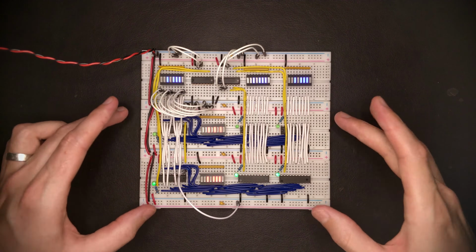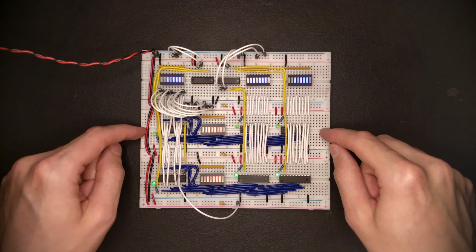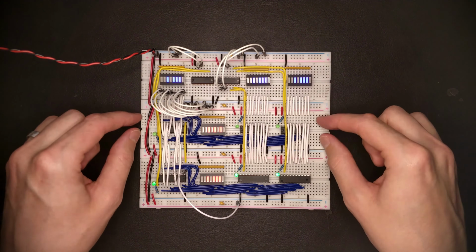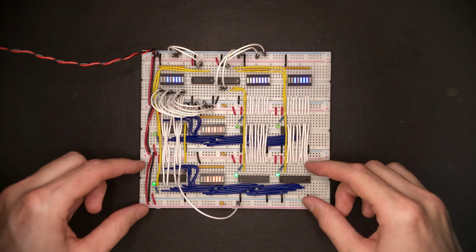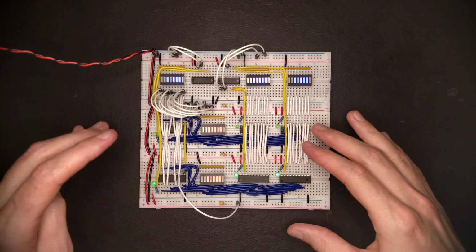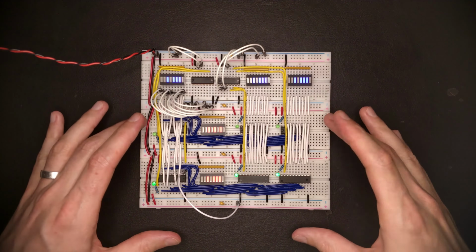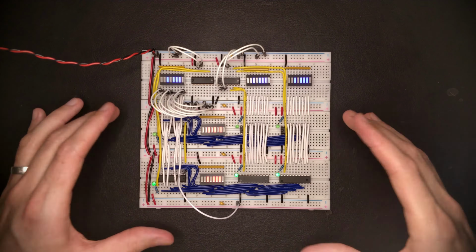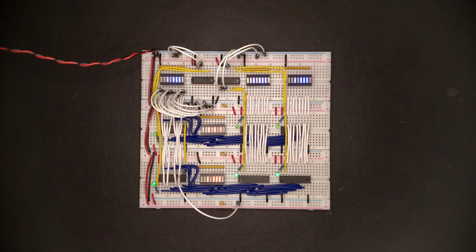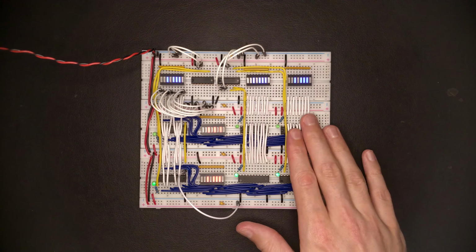And then in the future, what we probably are going to do is we're going to turn these registers into a PCB because the pattern is pretty repetitive and it has a lot of wiring. And then we'll have 4 of these PCBs arranged in a stack such that we can have 4 actual registers to work with. And I'm pretty sure we'll expand that as the CPU keeps growing and we expand also the functionality. Especially I have a suspicion that we want 3 read ports because we're dealing with a 16-bit system.